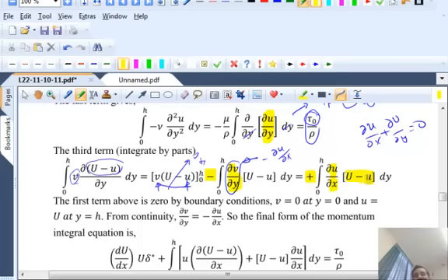Very perceptive question. You need to look at the Falkner-Skan solutions. When you're developing that, if the plate is inclined like this, you will set up a local coordinate. You will call this x1, you will call that x2. So u and v are still velocities that are parallel to and perpendicular to the plate. And that velocity would be 0. Now, if you have, what happens, this has also been done.